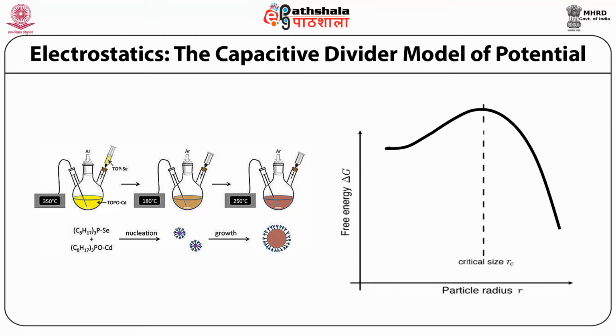So the chemical potential of the system when atoms are in the solution is less than that of the atoms in a crystal, and the minimum of the free energy is obtained when all the atoms are unbound. So no stable crystals are formed. However, we are interested in the opposite case, with the chemical potential of atoms in the solution being more than that of bound atoms. So the first term becomes negative, resulting in the free energy being a maximum for a certain critical radius RC at which the nucleation barrier is imposed, as shown in this figure.